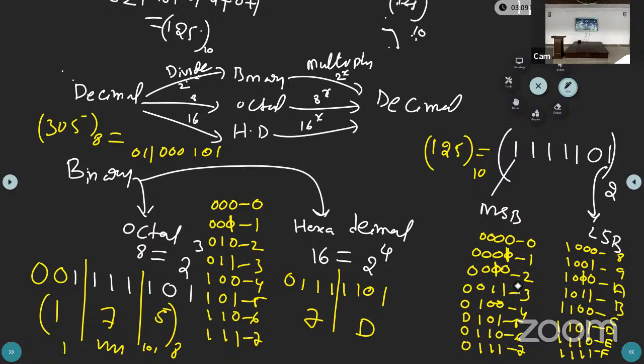Yeah, that topic is not covered. BCD to pure binary. BCD stands for binary coded decimal. Pure binary means, in BCD how many bits are we taking? 4 bits. In BCD, all the numbers are 0 to 9 only. The 0 can be represented as 0, 0, 0, 0. 9 can be represented as 1, 0, 0, 1. What is the BCD value after 9?